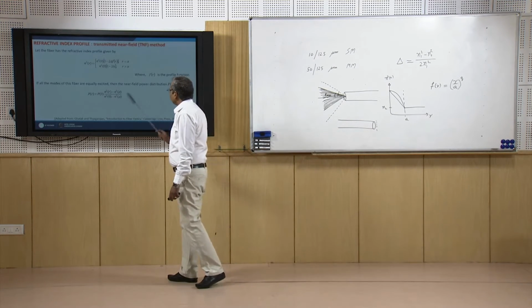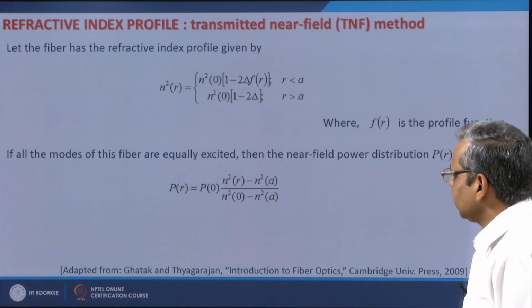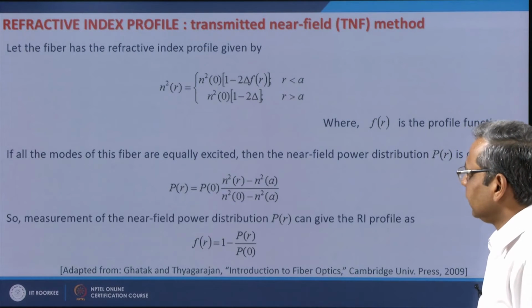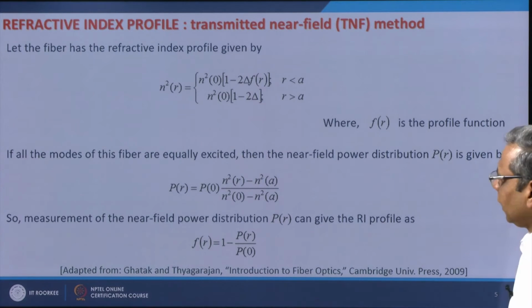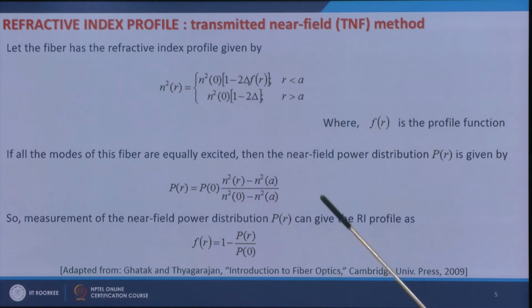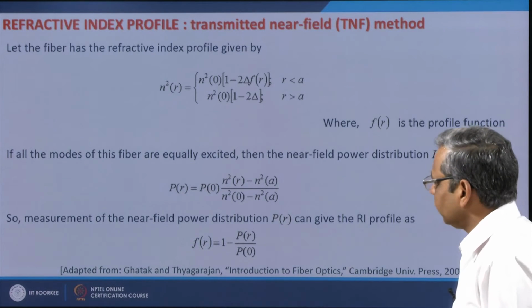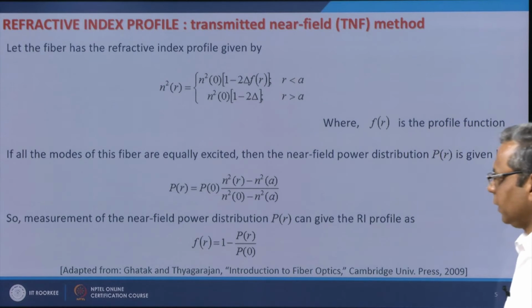So, the near field power distribution is given by this, and if I am able to measure this near field distribution, then from it I can find out the refractive index profile f(r).